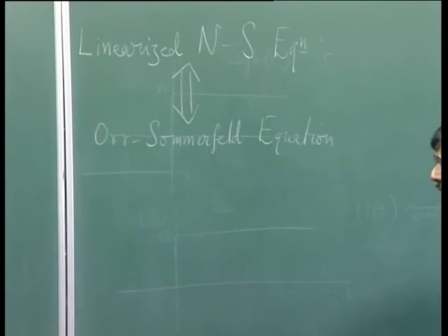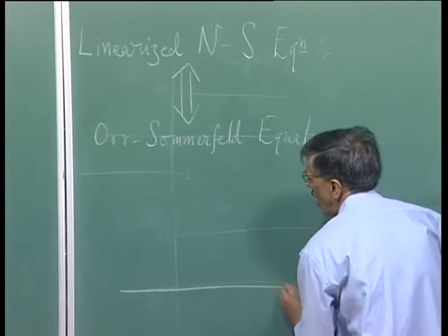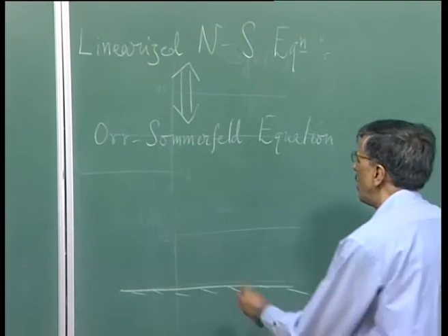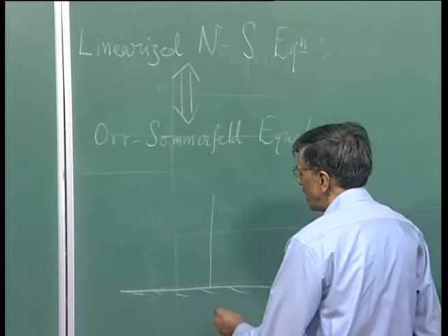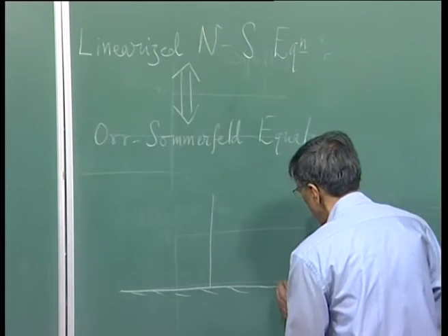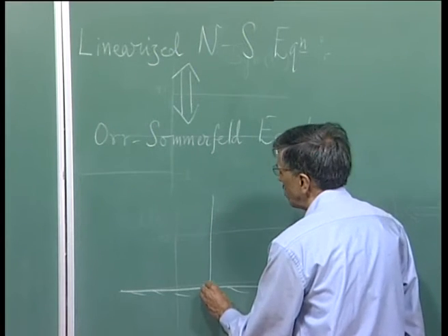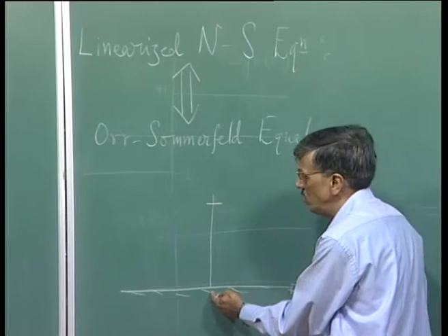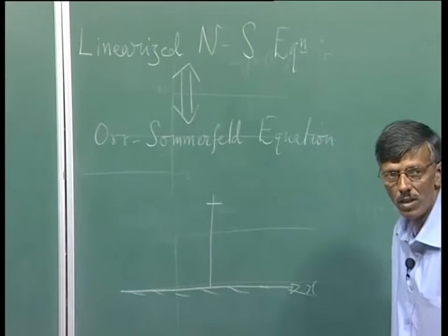Okay. And what happened? The Orr-Sommerfeld equation involves, let us say I have this flat plate. I want to study this. Now, what do I need to study? I need to study, at a given x location, what would I be doing? I would be solving the Orr-Sommerfeld equation from some limit of y equal to 0 to y going to infinity, a large value.